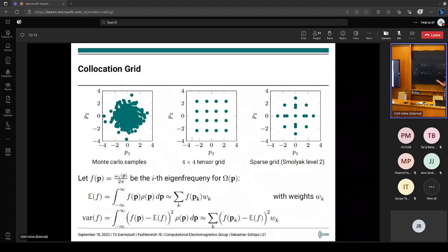And so the first one is not necessarily the one you want to follow, right? Because at that point, maybe this was the smallest eigenvalue. So we were interested in doing uncertainty quantification maybe for this one. This is maybe then the second largest. Then we do deformation, and we should not follow this one, but we should follow this one after the deformation. So what that required us to do was a so-called tracking procedure. We basically didn't modify the geometry in a big step, but always changed it in very small increments and then tracked it back.